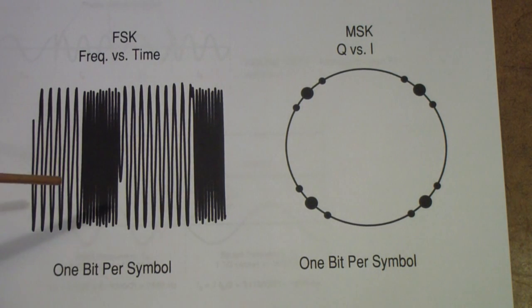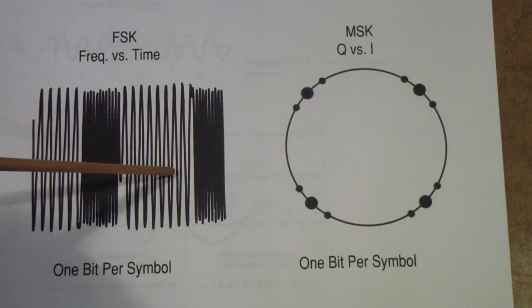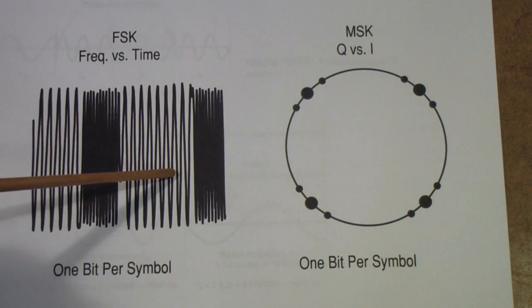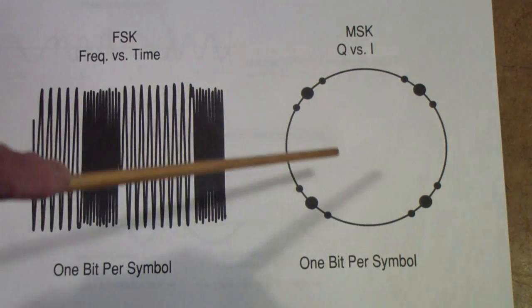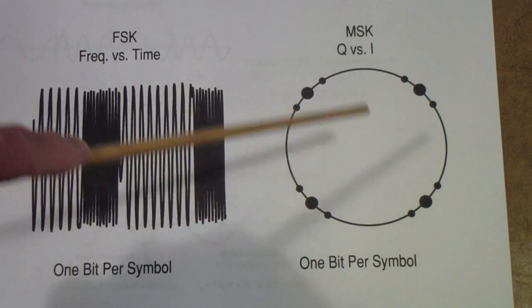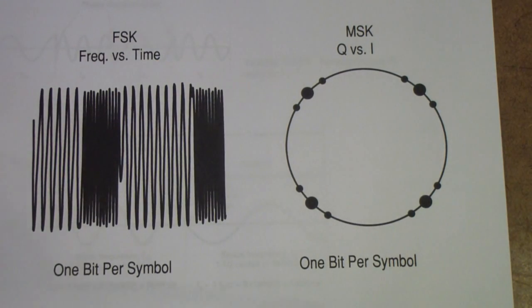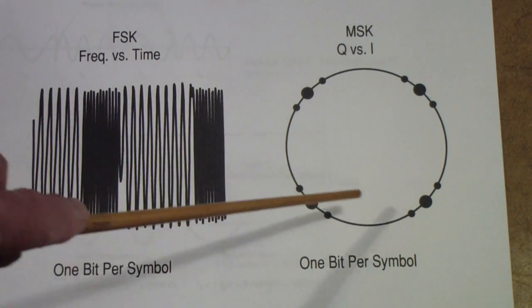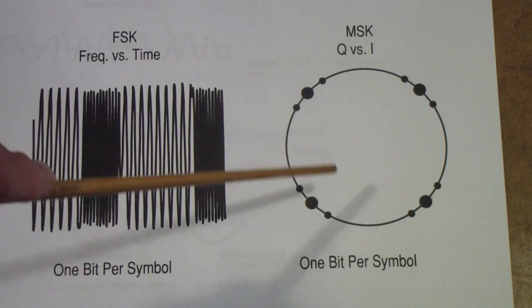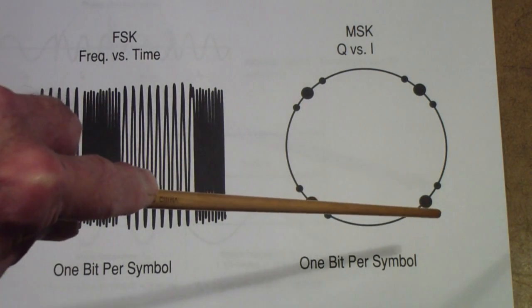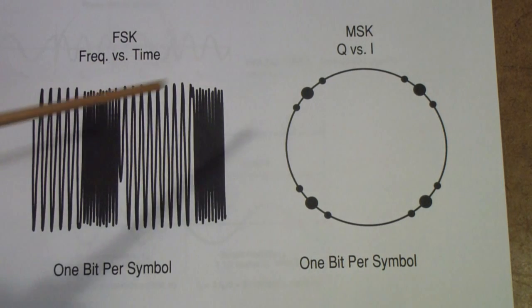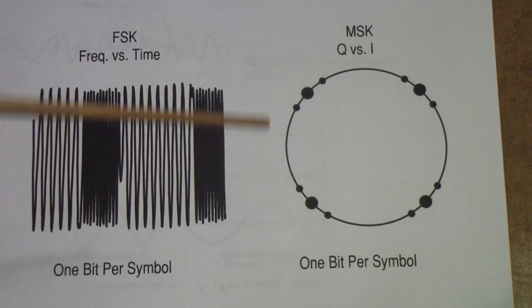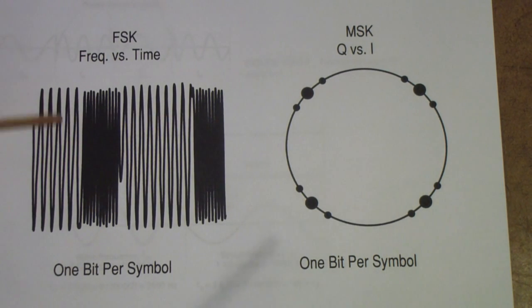That is, this shows a typical frequency shift keyed signal. In MSK, what you are trying to do is to actually get the carriers, that is the mark and space frequencies, to be phase coherent, so that when it shifts from a mark to a space or a space to a mark, it does so at a time when the two signals are at zero.